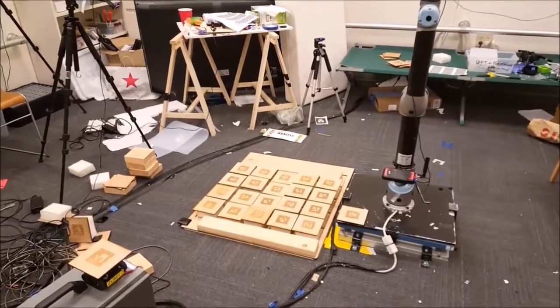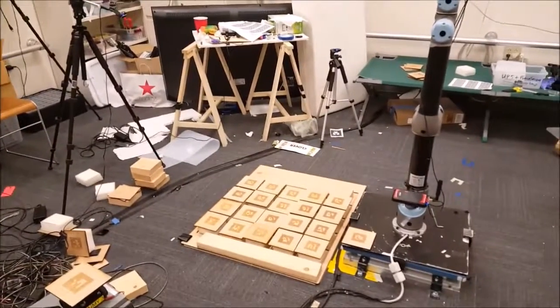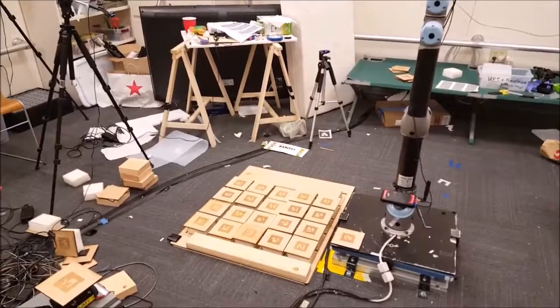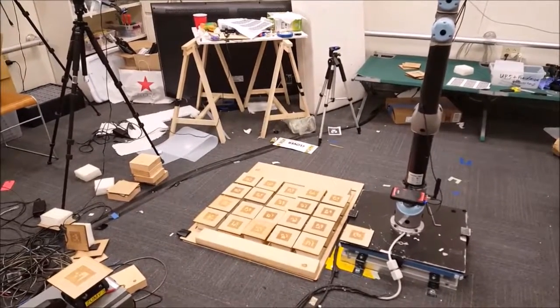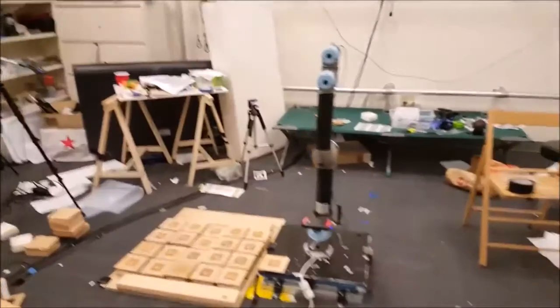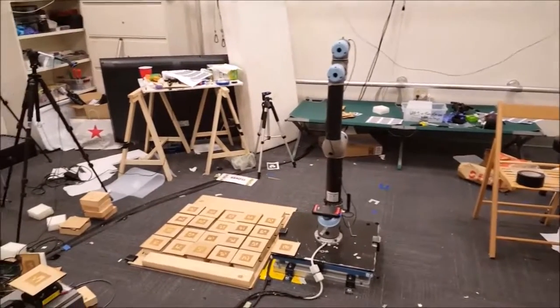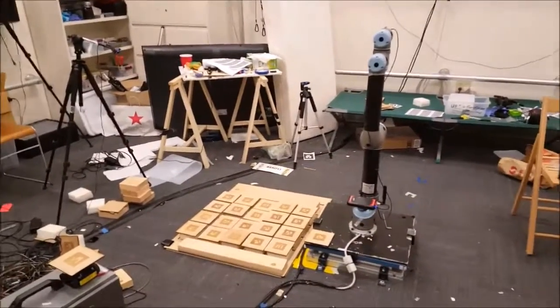So, as you can see, we have this camera mounted on a tripod that's looking down on this grid of AR tags. What it's doing right now is it has mapped the positions of these AR tags into an array that we're going to store and use with the UR5 robot when it's performing inverse kinematics and traversing the grid